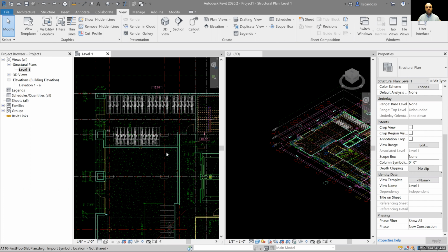From here on out, Revit wants vertical elements. It wants walls and columns, okay? Because as you get used to using Revit and you understand what it wants to be linked to, you understand that floors link to walls and foundations link to columns. So let's play on that and let's start modeling.